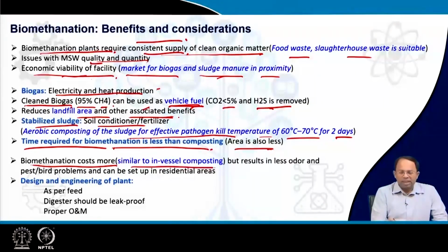But it is similar to in-vessel composting. Sorry. But the benefit of biomethanation is it results in lesser odor, and because it's a covered process, it happens in a chamber, pest and bird problems are not there, and this can be set up in residential areas and it doesn't pollute, right? So that's the benefit of biomethanation. So it's a bit costly, but at the same point of time, we can have it in a more decentralized fashion. So design and engineering of this particular biomethanation plant has to be